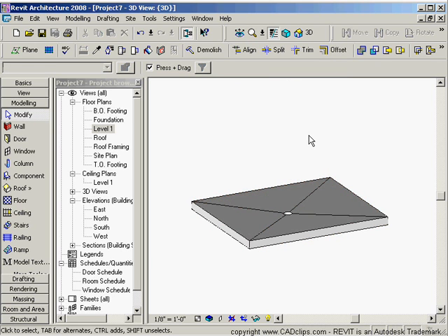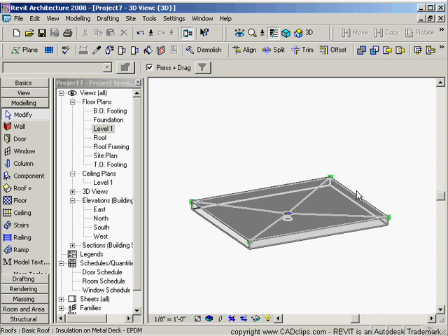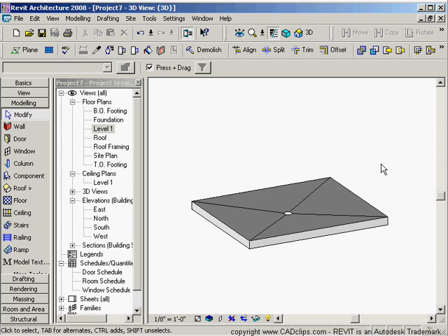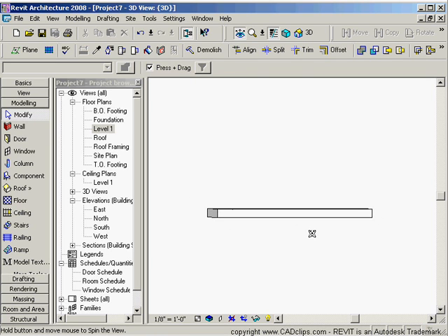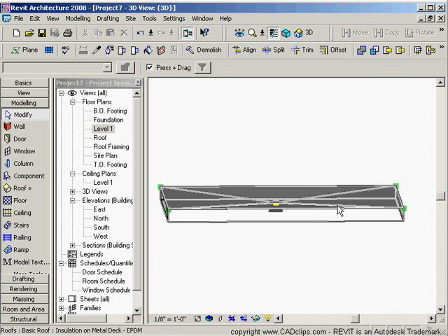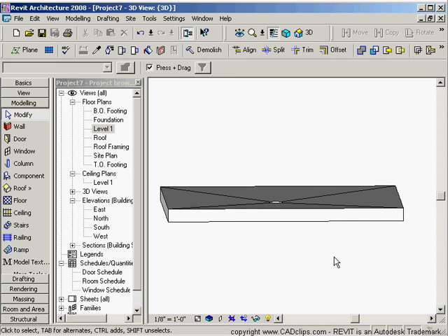And there's another nice feature with 2008 REVIT is that you can have one of the components or layers within that floor or roof structure have a varying thickness. You can only have one of the components be variable, and when you add a slope, it maintains the bottom of the floor or slab straight, and one of the components within that slab will take up the slack.